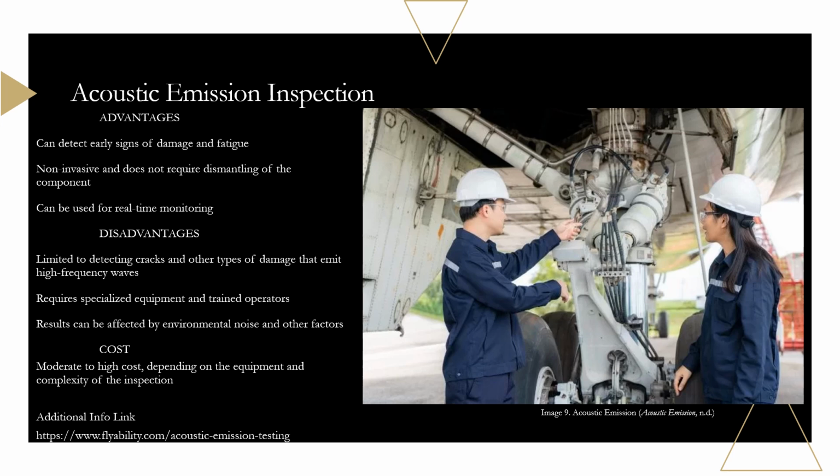Lastly, we have acoustic emission testing. This test can detect early signs of damage and fatigue and can be used for real-time monitoring. It is non-invasive and does not require dismantling of the component. However, it is limited to detecting cracks and other types of damage that emit high-frequency waves, requires specialized equipment and trained operators, and its results can be affected by environmental noise and other factors. The cost is moderate to high, depending on the equipment and the complexity of the inspection.